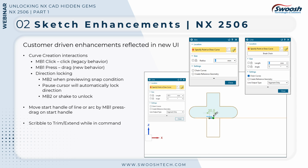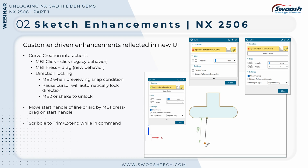There's also enhanced locking options during curve sketching. You can lock the drawing direction for precision, use the secondary or middle mouse button to lock the current direction. Alternatively, you can pause your cursor and NX will automatically lock it for you. To unlock the curve, simply press the middle mouse button again, or give your mouse a quick shake to release the lock condition.